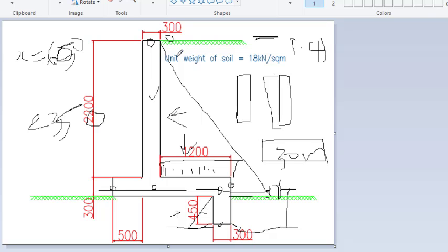So you'll be having a triangular load here, and the value will be 9.81 kilonewton per meter squared. And here we'll be having a UDL, which will be 9.81 multiplied by the height, and we said we want the water to be to the brim, which will be the maximum, so that will be 9.81 multiplied by 2.2. That will be the load on this portion.